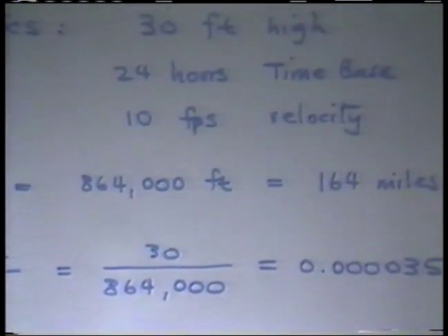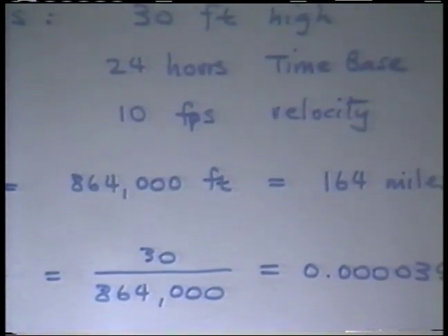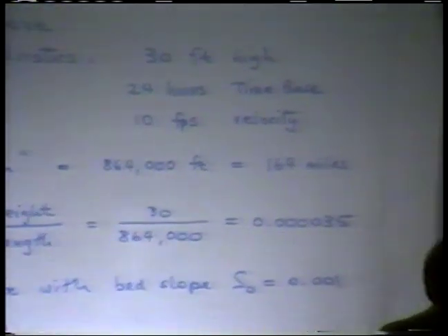So let's say we have a wave velocity of 10 feet per second. That is not unreasonable either. That would be typical of a fast-moving stream, 10 feet per second. If that is the case, then we can say that the length, because the celerity is equal to the length over the time, when you talk about sinusoidal waves, this is in fact a formula that could be used.